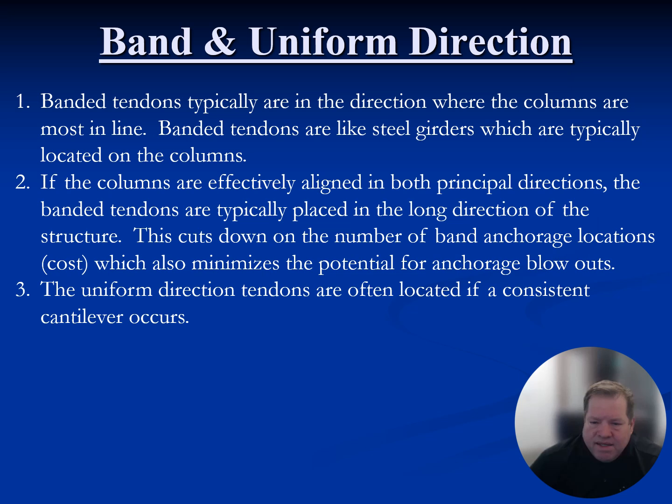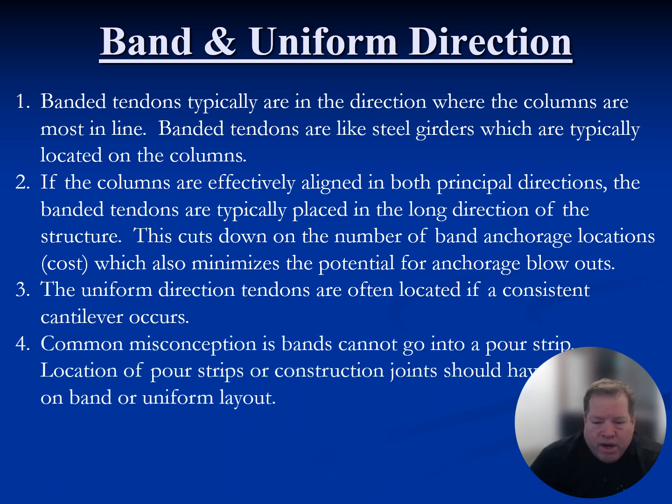If you have a consistent cantilever, everything off grid, say a 5-foot, 6-foot cantilever, we typically try to put the uniform tendons in that zone. This is not a code issue. There's nothing wrong with having bands go to the uniform, but as a general concept, when you have a uniform loading on a cantilever, we'd like to match that with uniform-spaced PT. So if that works out and we do have a consistent cantilever, we put the uniforms in that direction.